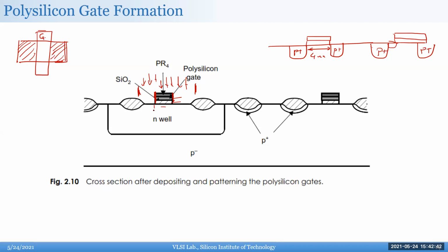And then what it does, by virtue of the polysilicon masking it, it will just implant the ions in the source and drain area. Underneath the gate, it will be stopped by the polysilicon. Okay. And the gate, you ideally want it to be metal.